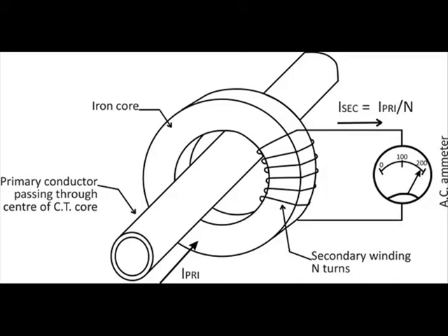In this work, it's about current transformers and their application as current sensors. A current transformer is a type of instrument transformer that is designed to produce an alternating current in its secondary winding, which is proportional to the current being measured in its primary. Our current transformer design has 5 turns in the primary winding and 78 in the secondary winding.